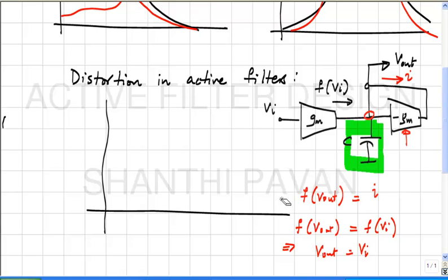of x is x, no matter what f is, as long as it's 1 to 1, you find that the input is the same as the output, and again you could get conned into believing that the filter is extremely linear, even though it actually could be far from it. You understand? So putting in very low frequency inputs doesn't make sense. Putting in very high frequency inputs or inputs near the band edge also does not make sense, because the harmonics then are filtered out by the filtering network.